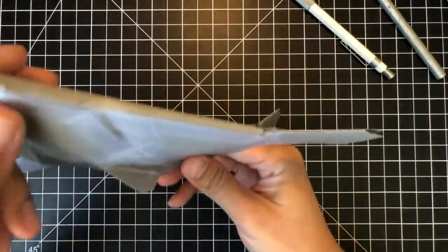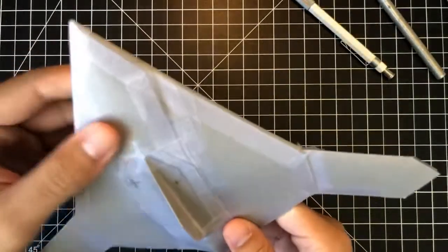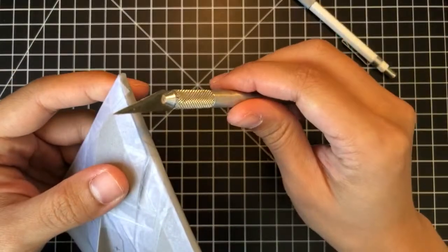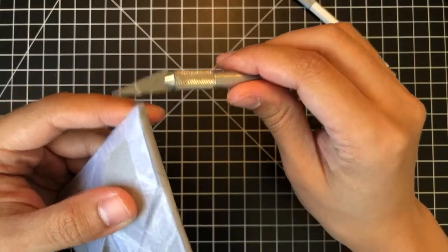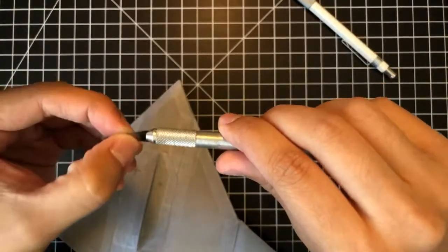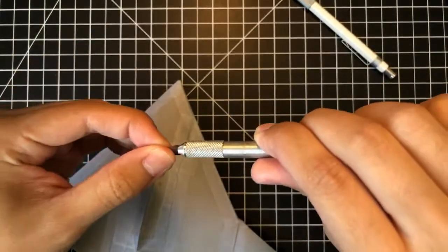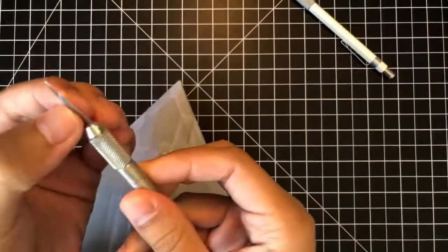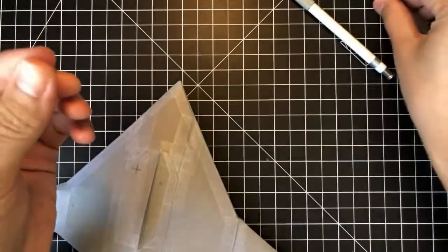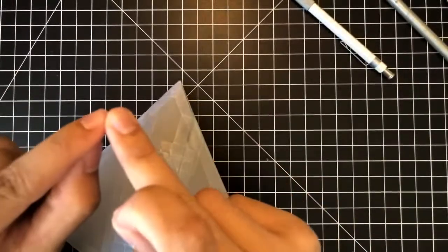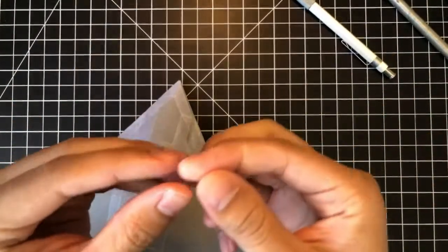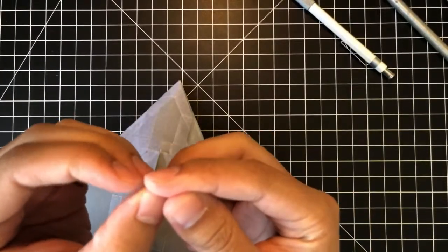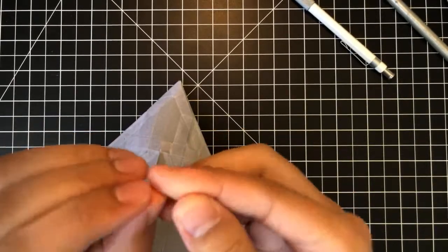Aerodynamically speaking, it's a measure of effectiveness in keeping your plane aloft, right? An L over D of 40 essentially means for every 1 foot drop in elevation, you go forward 40 feet. So it's a 40 to 1 ratio basically.